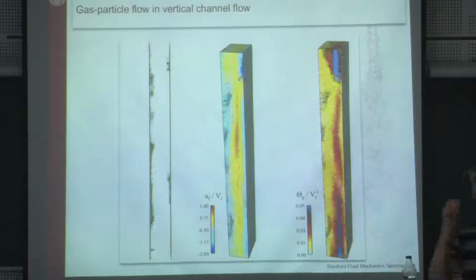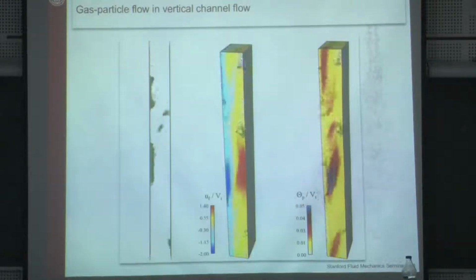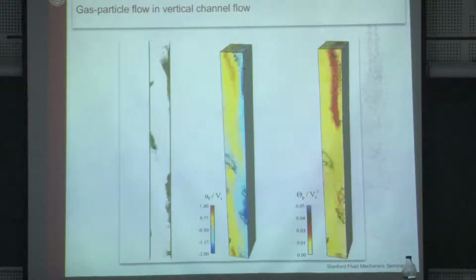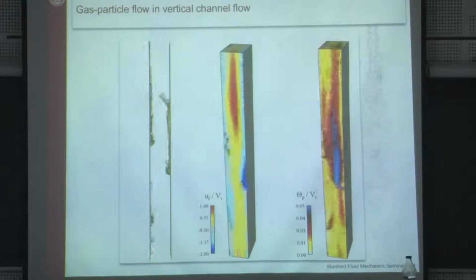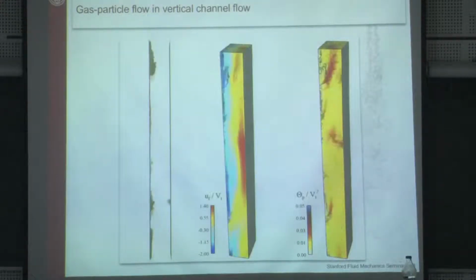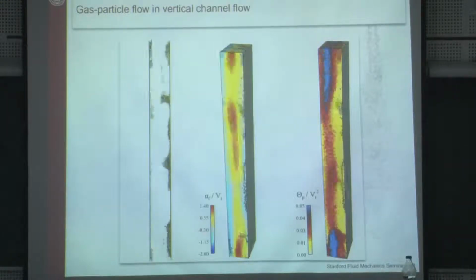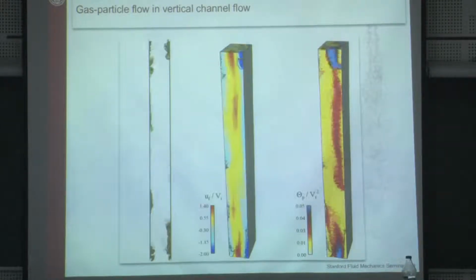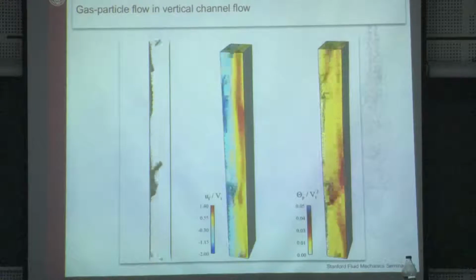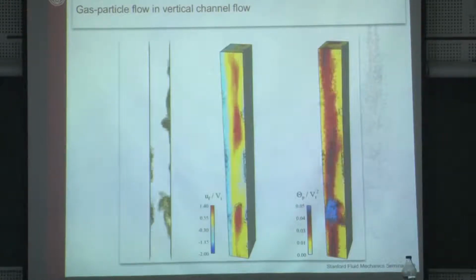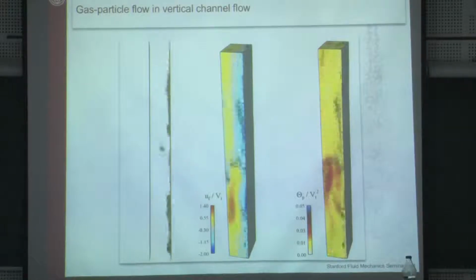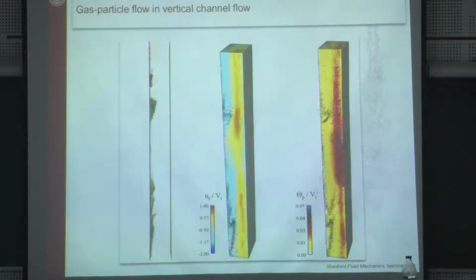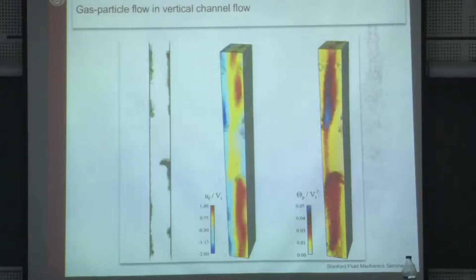Now, what if I put walls? So we were looking at those big clusters, left alone to develop on large domains. As soon as I put walls, provided those walls are not significantly wider than the capital L cluster lengths that we've defined, suddenly the clusters can't develop freely, and they're going to be constrained by the presence of the wall. What's going to be happening? Well, those clusters are going to accumulate in the walls where it's favorable for them to be, because there is no fluid velocity pushing them up because of the hydrodynamic boundary layers. So you end up in situations like this.